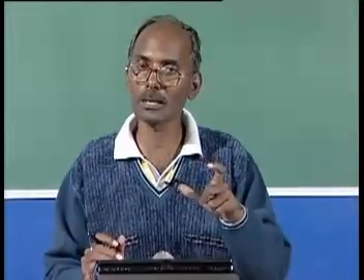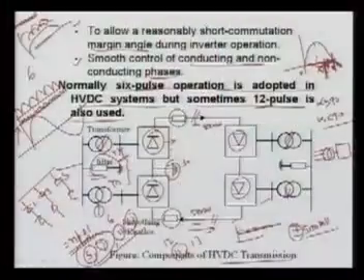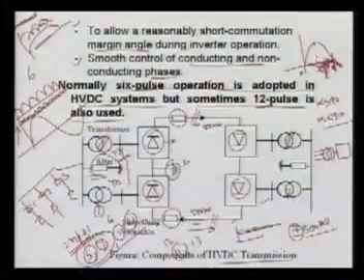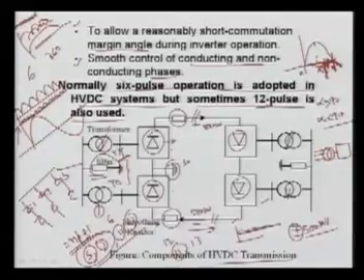Automatically, the 2 6-pulse converters are connected, because we have the inherent property of this 3-phase connection, 30 degree lead. So here, in 360, earlier it was 60, 60. Now we have shifted 30 degrees, and 60, 60. So in 360 we have 12 pulse operation, and the same 3-phase transformer is very good for using the 12 pulse, and normally we go for the 12 pulse operation rather than using 6 pulse to 6 pulse bridge converters. So this converter operation and its analysis, its performance is very important, and if we have time, then we will discuss that as well.